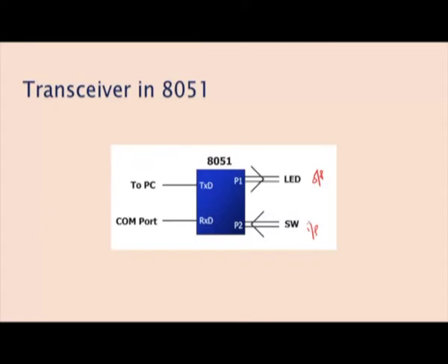Suppose externally data is received and we want to transmit. Okay. So, externally, 8 switches are connected. If any one of the switches is pressed, or you can use a single switch with continuous 8 pulses. The signals from the switches are sensed or read via port 2. This port 2 signal is moved to SBUF, right. From the SBUF it will be transmitted. This is one way.